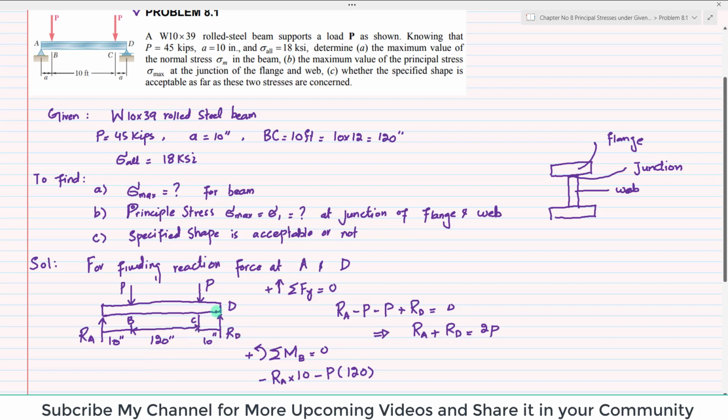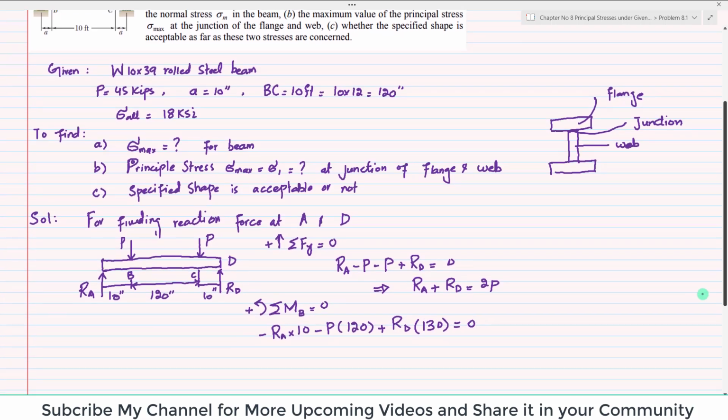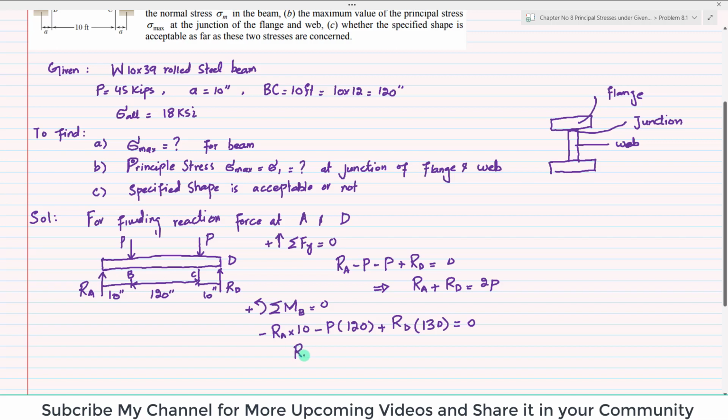And this force is producing moment about point B equal to plus Rd into perpendicular distance 120 plus 10, which is 130. Their sum must be equal to 0. Further simplifying, this will be minus 10 Ra minus 120 P plus 130 Rd is equal to 0. Clear?